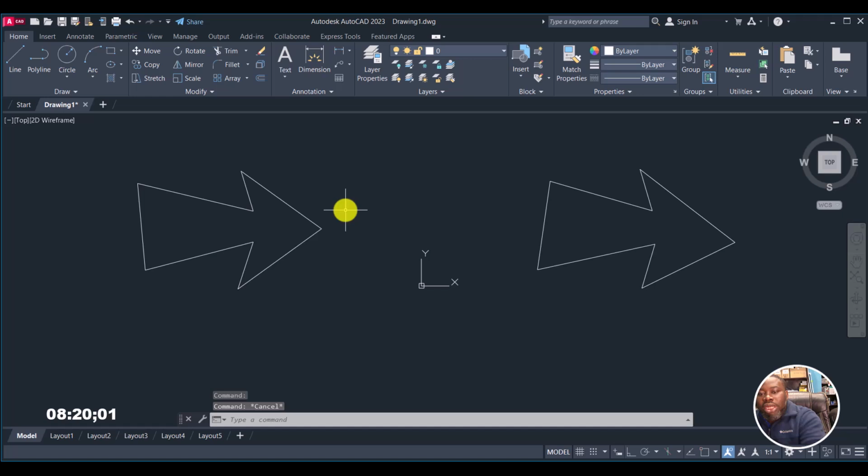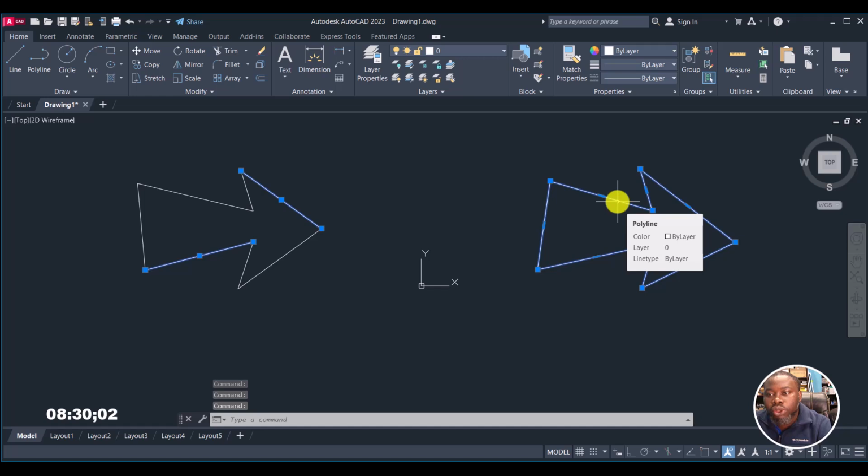Okay, all right. So now with line, you have individual objects. With polyline, all of this is just a single object. They are all connected. It's a single unit. So this is another difference between line and polyline. And this difference is more of importance when you are dealing with 3D, when you are working with 3D. All right. So now that is line and polyline.